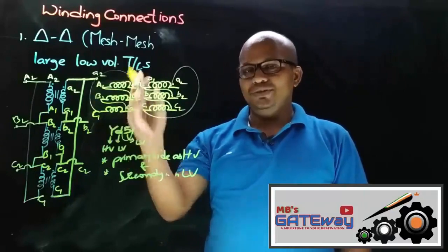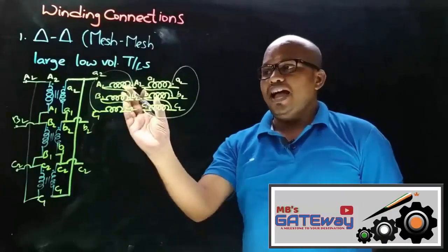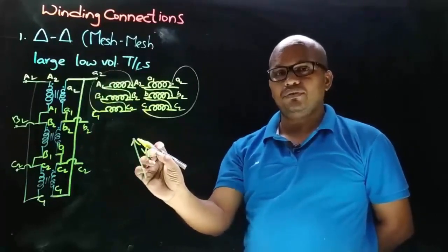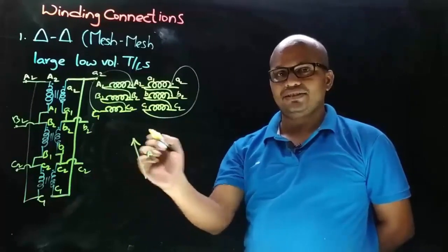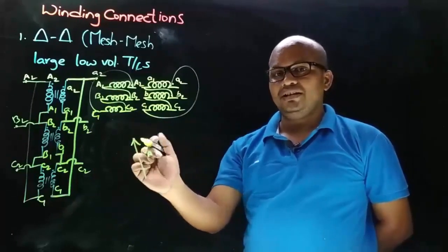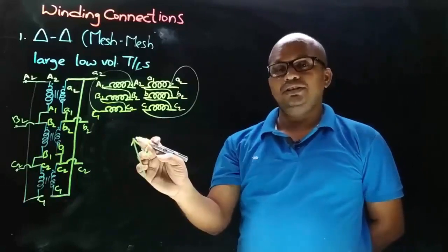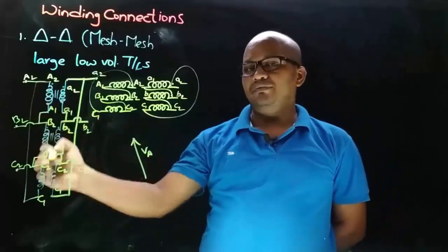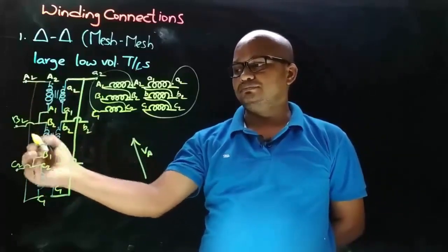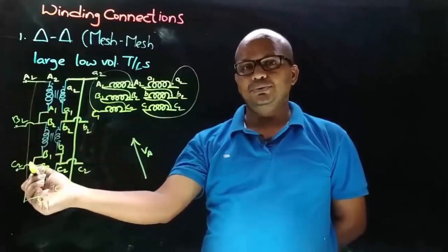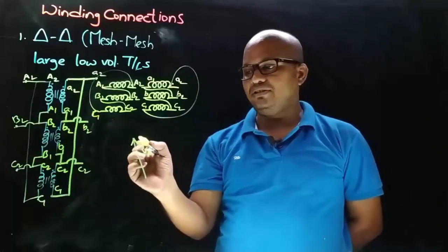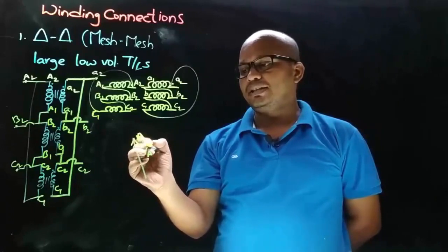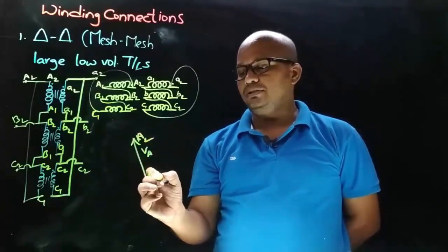Now let's continue with this phasor diagram. As the primary side is delta connected, for our convenience, let's consider the primary side VA phasor like this, and here our task is to decide the terminals of this. The arrow always points towards the connection we took from. So on the primary side we took the connections from the dot ends, that is A2, B2 and C2 terminals. As this is the primary side VA phasor, this arrow will have the terminal capital A2. So this will be capital A1.